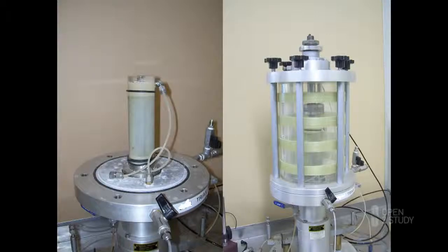You can notice on the left of the photo that the specimen is placed in a rubber membrane. That is to prevent water from getting into the specimen. The black lines are actually O-rings, that is little rubber bands holding the membrane tight around the loading cap and the pedestal so that water doesn't get in. Through the top of the bell passes a piston. The piston rests on the loading head that is on top of the specimen, and the piston is used to exert a vertical load onto the specimen after the confinement has been applied.